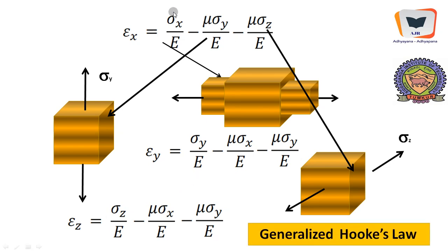These equations in general, that is the net strain along x, net strain along y, net strain along z, are conjointly called as generalized Hooke's law. And simple Hooke's law happens to be associated with only one unidirectional stress. Okay, and that is stress is proportional to strain.